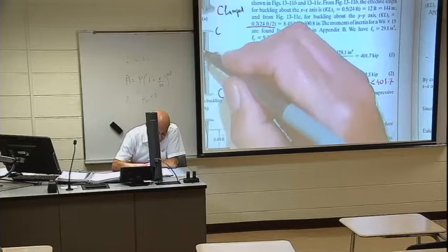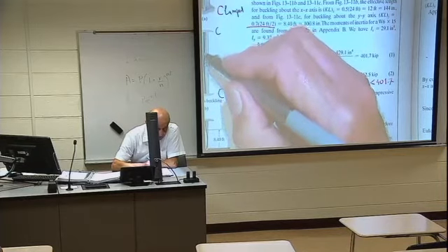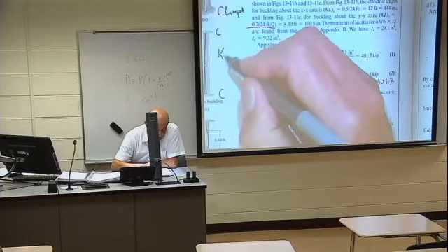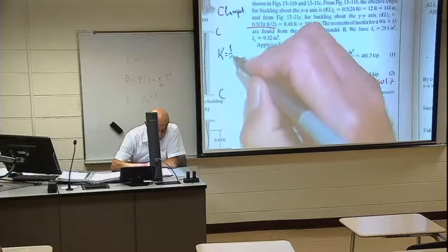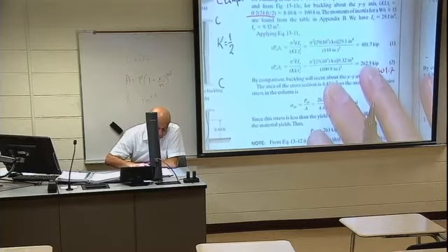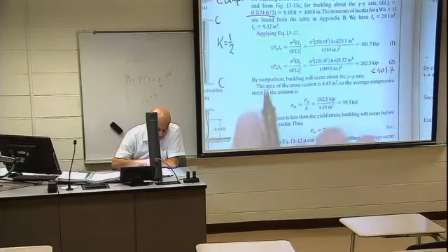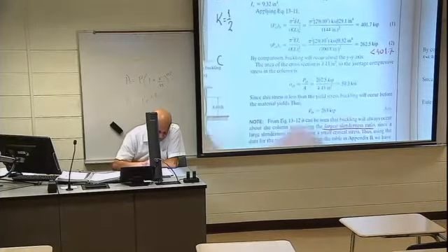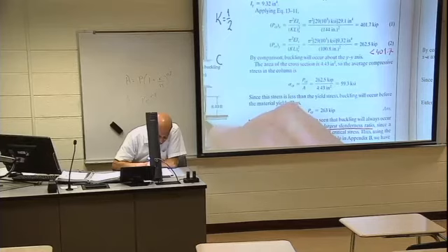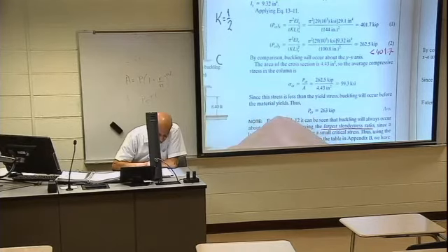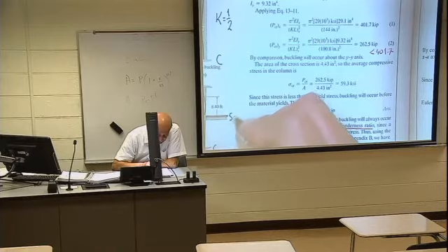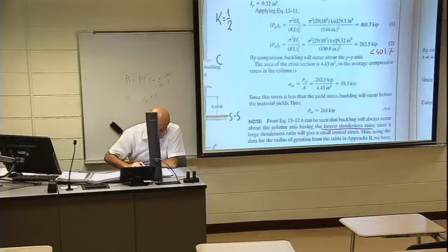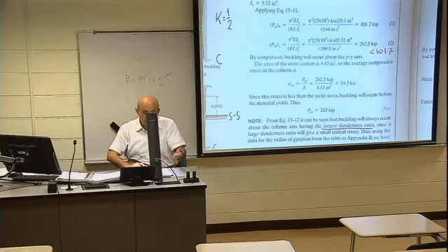Do you remember we showed that the effective length coefficient for a clamped column is 1/2. Now, second, in the other direction where the bracing occurs, we said bracing makes simple support. So here below will be clamped, and here will be simply supported. So then it is 0.7, okay?